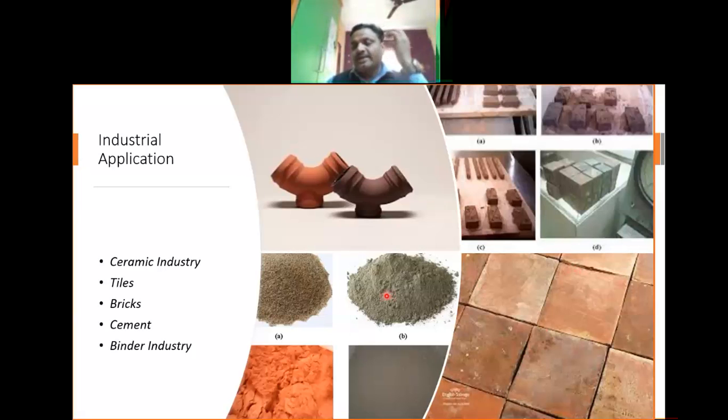Our Hindalco unit has an MOU with our Ultratech plant, where part of the raw material for aluminum and calcium has been replaced with this red mud and is being used for cement manufacturing without affecting any binding property of cement, and in mixing with other binders, it is also being used as a good binder. Other than that, as I showed, it contains about 20% of alumina and 35% of iron.